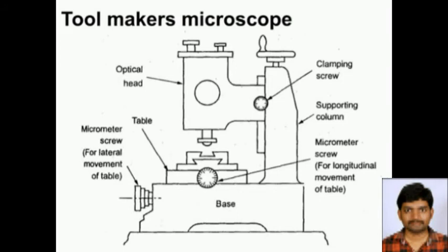Different types of graduated and engraved screens and corresponding eyepieces are used for measuring different elements. For example, a revolving screen for measurement of standard threads will contain all the basic profiles of all standard threads in various pitch ranges and also various included angles of the thread. By using this we can measure linear dimensions, the pitch of a screw, and thread angles, etc. So by using this instrument we can measure like this.